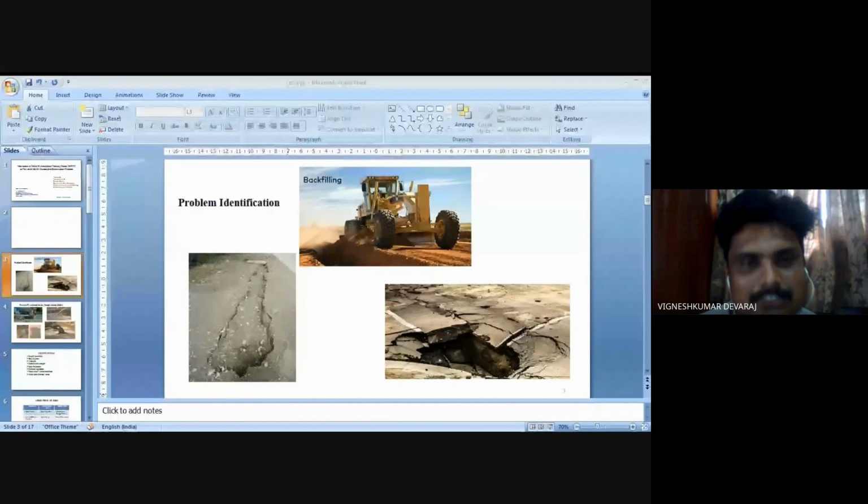It is a mixture of Portland cement, cementitious material such as fly ash, and a measured amount of water. It has very good characteristics of self-leveling and self-compacting. Two types of flowable fills are available: one is excavatable and the other is unexcavatable. Both need a flowability of 200. For excavatable conditions, we need a strength of 0.7 megapascal. For unexcavatable conditions, we need a strength of 8.1 megapascal.